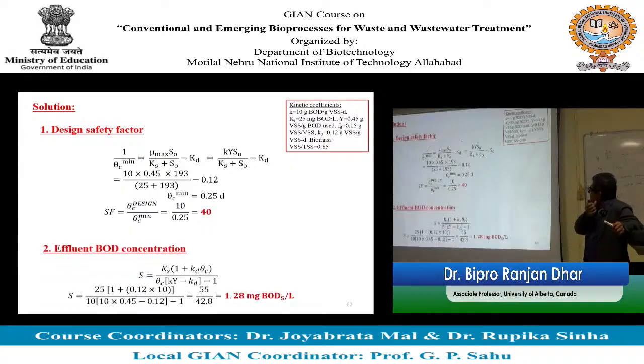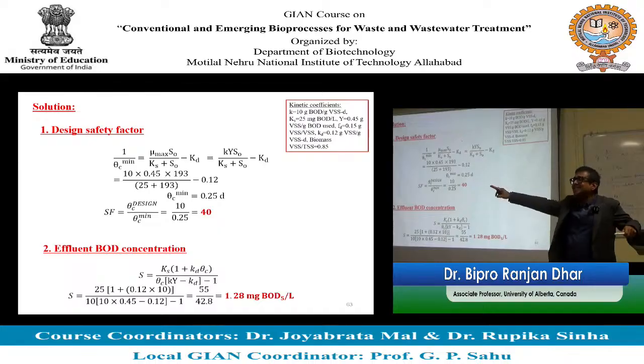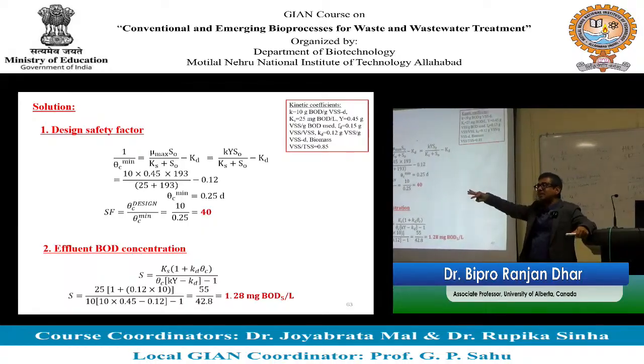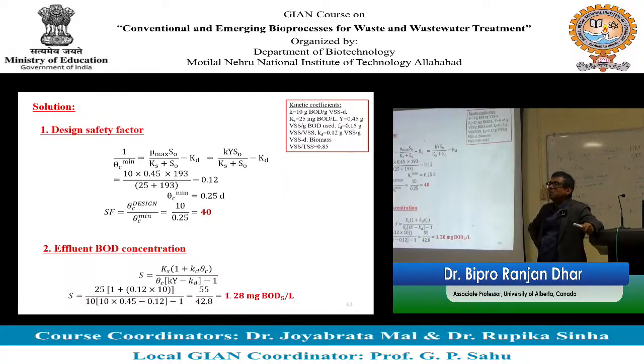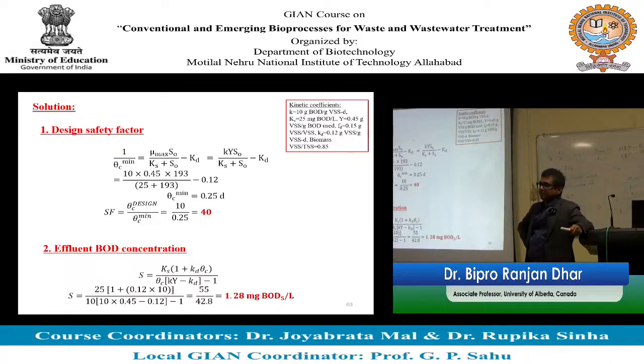Sometimes there could be a problem if you maintain really high SRT. Some microbes might grow in the system that may not settle very easily. That could be problematic too. So too long an SRT is not good either.